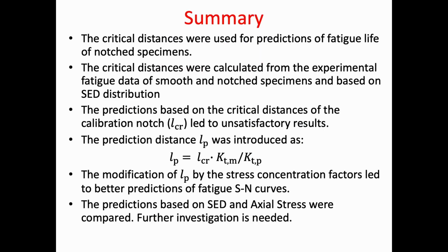So let me conclude. We have used the critical distances for fatigue lifetime predictions of notched specimens. The critical distances were determined from experimental fatigue data of smooth and calibration notch specimens and based on strain energy density. When we use critical distances as they are, they lead to quite unsatisfactory results.